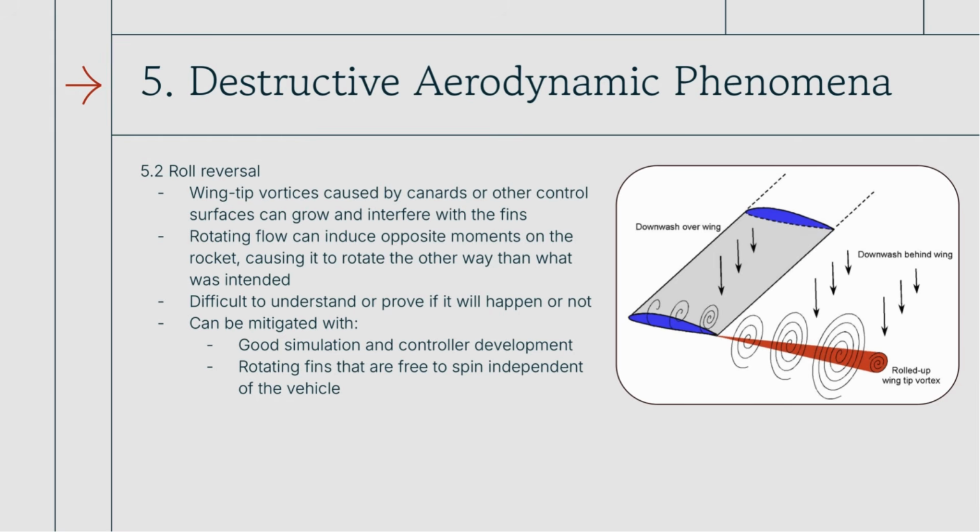But because the wings are finite, basically high pressure from underneath the wing tries to compensate and go to the other side of the wing, to re-equilibrate the pressure on both sides. It's going to try and go around the tip of the wing. And in doing so, it causes rotation in your flow. And that rotation is a vortex that grows behind the wing. So you can see it starts out really small and curled, and then as you go behind the wing, it increases in size.